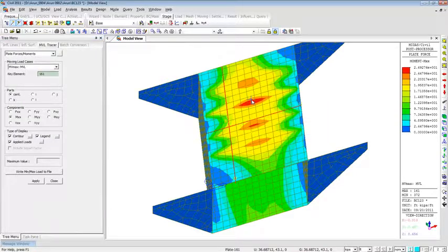So I'll click on this element. You can see the element number entered here. I can choose either the center or the four corners I, J, K and L going in the direction of the plate generation. So let's say I want to see it at the Jth end. Again, I'm looking for MX6, and then I'll click on